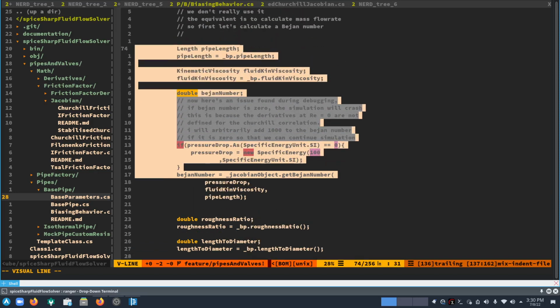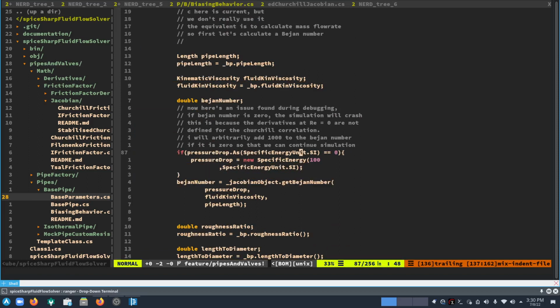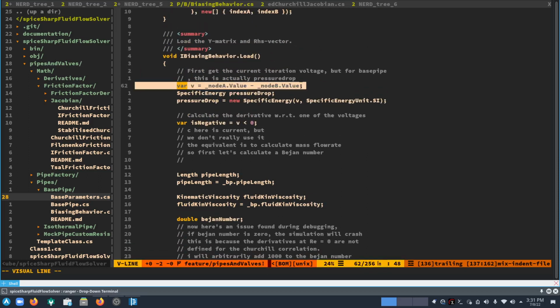Okay, so all of this is okay, but usually when we start calculations, all the values at node A, node B, all the pressures will be equal to 0. That's what I found out when I started. So that is a problem, because when we have a 0 pressure drop, our whole way of calculation will be haywire, because these functions do not behave very well at pressure drop equal to 0.